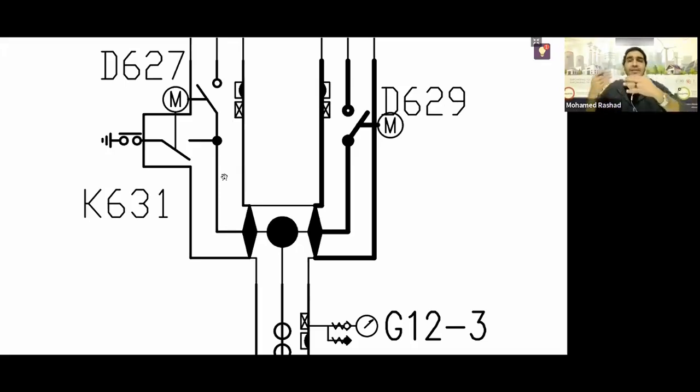The hydrogen present in the water vapor molecules decomposes, but of course in very, very small amounts. If it combines with fluorine atoms, it forms something called hydrogen fluoride. I told you that hydrogen fluoride is a chemically corrosive material, meaning it eats away at parts like the insulators, especially the spacers, and it erodes the epoxy itself. So, of course, it destroys the insulators, which is what the absorbent prevents.